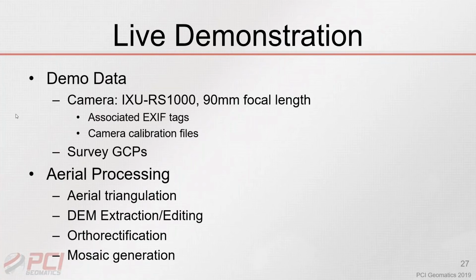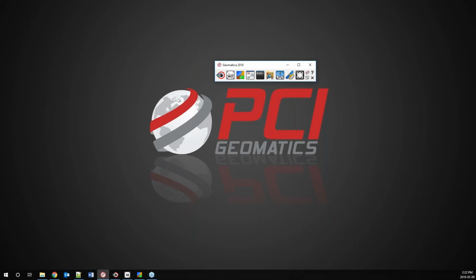Hello, everyone. For this demonstration, as Kevin mentioned, I will be demonstrating and showcasing the full Geomatica workflow as presented by Kevin. I will demonstrate how a user can prepare a new Ortho Engine project, ingest the raw PhaseOne imagery, improve the aerial triangulation of the model with ground control points and tie points, extract a DEM, edit and filter the DEM to then generate the ortho rectified imagery, and then produce the final DTM mosaic.